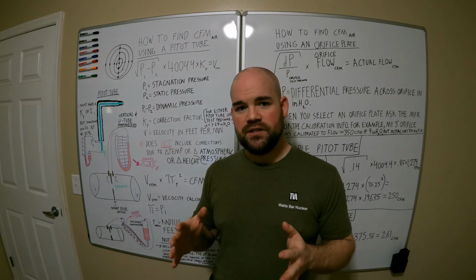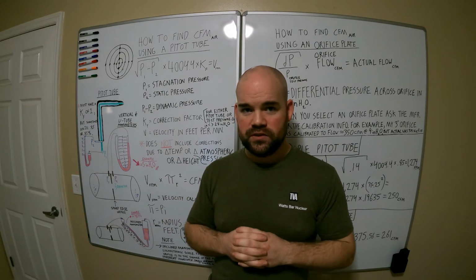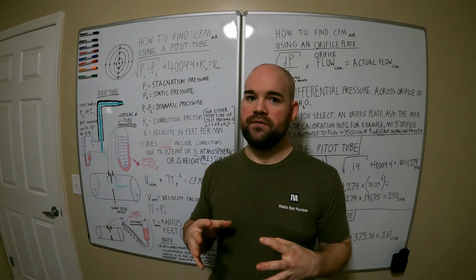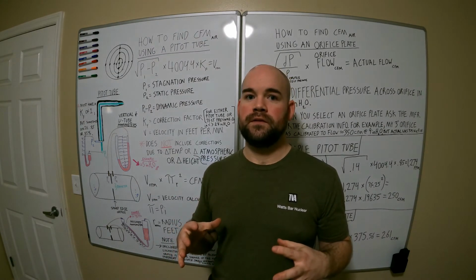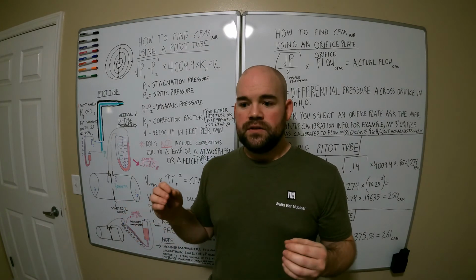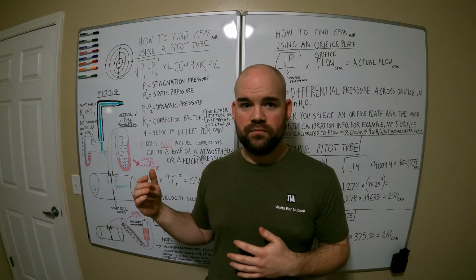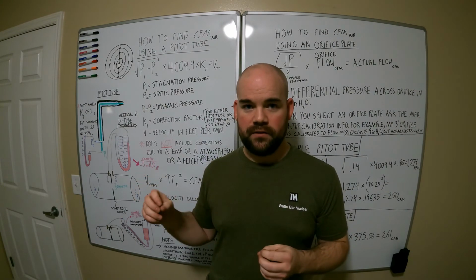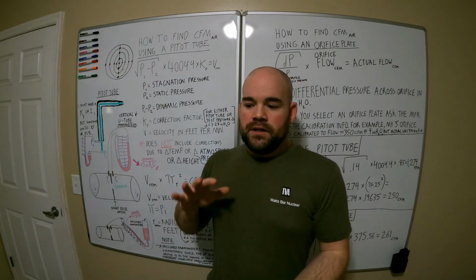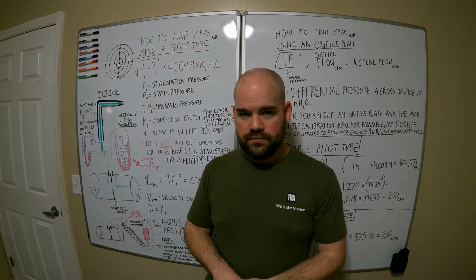The only thing that changes with boost, when you cram the molecules closer together, is you're increasing the oxygen content of that 1 cubic foot, okay? More oxygen means more fuel, more power, right? So more airflow doesn't make power, more fuel does. But the only way to burn that fuel in the right air-fuel ratio is to get the right oxygen level in this engine. So when you add boost, you're not forcing the air through the engine, okay?